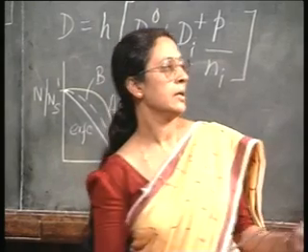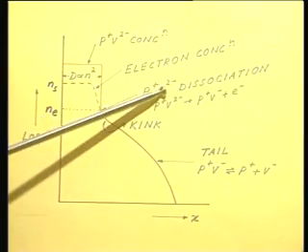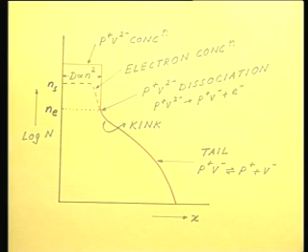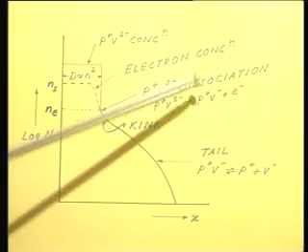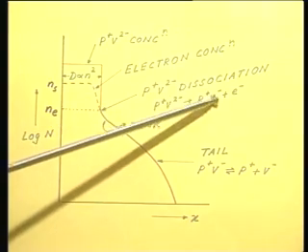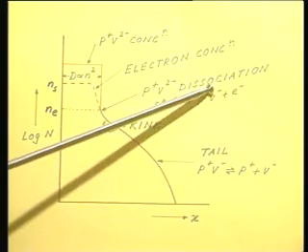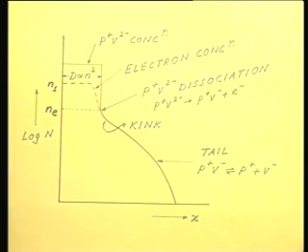So, then this is the significance of this, that then these doubly ionized vacancies begin to release electrons and it dissociates. See, P plus V2 minus dissociates into P plus V minus, that is a singly negatively ionized vacancy, and it releases 1 electron because the Fermi level is now sweeping by.